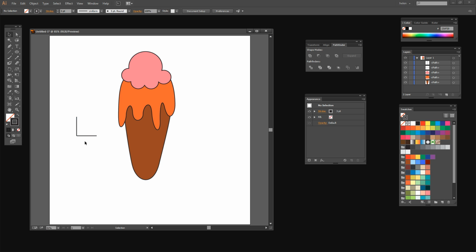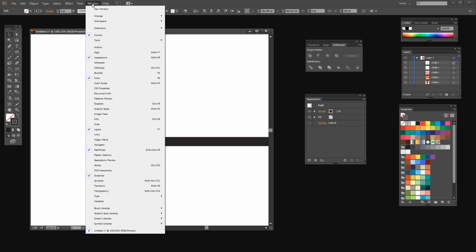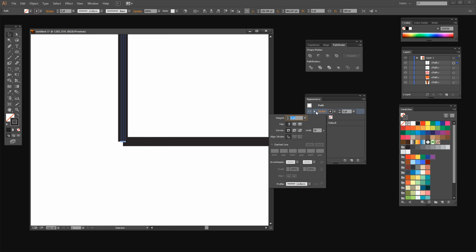I'm going to move the first line down on top of the second so that they intersect. I'm just going to make sure that they do intersect properly because this is going to be the corner of my shape. Now, if I go and change the strokes on these lines, they're going to work a little better. So with this line selected, I'm going to the Appearance panel, and you can get to that by choosing Window, Appearance. And I want to click open the stroke here, and I want to set my stroke to a projecting cap.